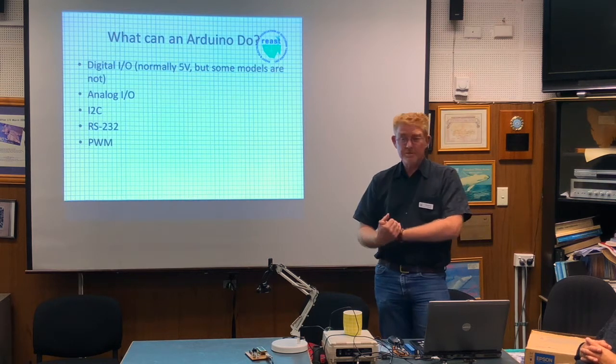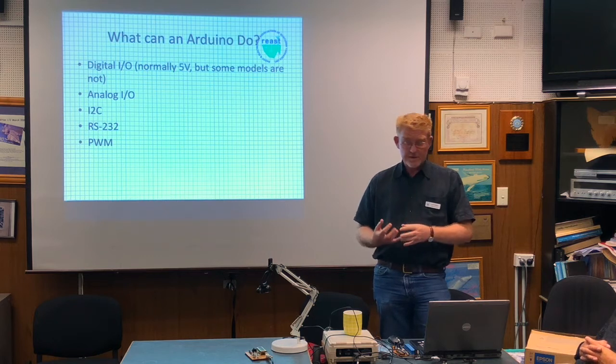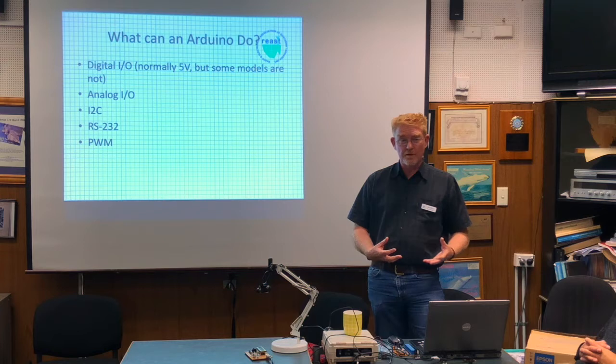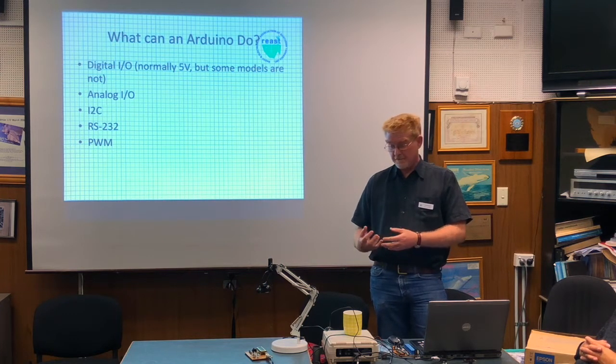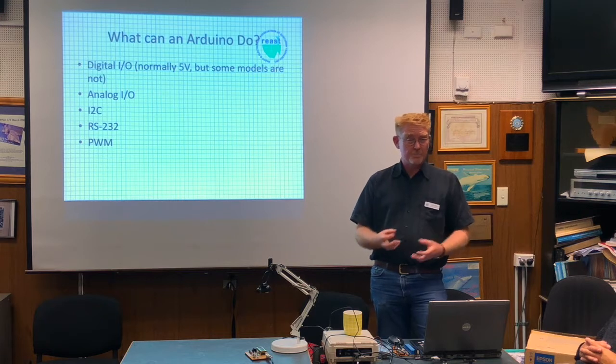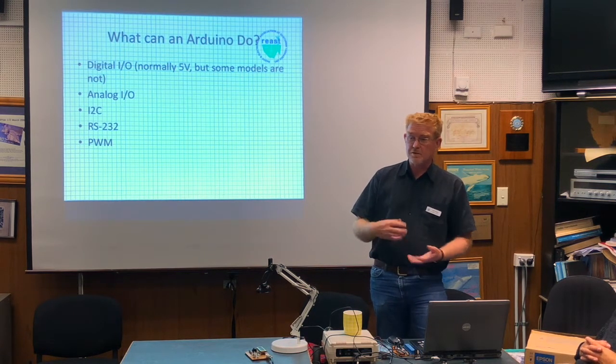What can the Arduinos do? Like I mentioned, they're normally a 5-volt device. There are some that can do 3.3 volts if you're using different technology, so you don't have to worry about things like level converters. They have analog I/O, so you can read a potentiometer. They can do analog output through PWM to generate varying voltages between 0 and 5 or 0 and 3.3.